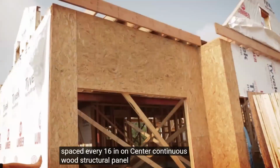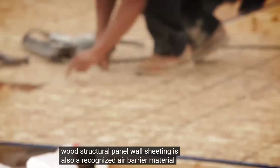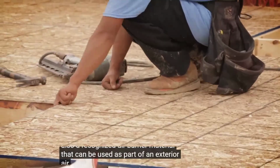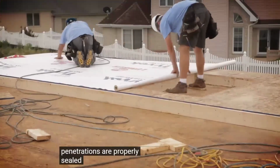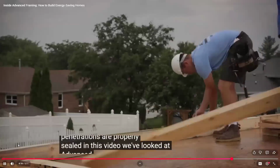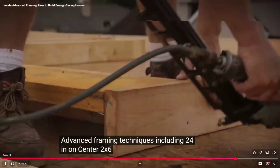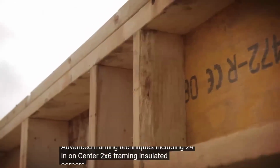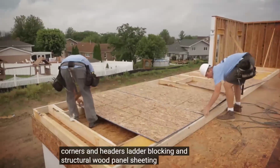Continuous wood structural panel wall sheathing is also a recognized air barrier material that can be used as part of an exterior air barrier system when joints and penetrations are properly sealed. In this video, we've looked at advanced framing techniques, including 24-inch on-center 2x6 framing, insulated corners and headers, ladder blocking, and structural wood panel sheathing.